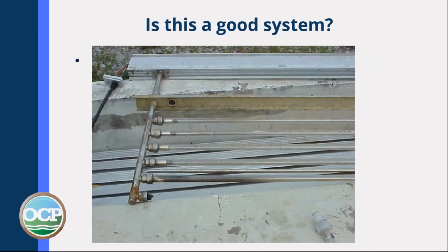What would you think if you saw this system? You were at a wastewater plant and saw this. Do you think that's a good system? There are broken bulbs, the sleeves aren't changed. It looks like a couple of the lights don't even have sleeves on them.